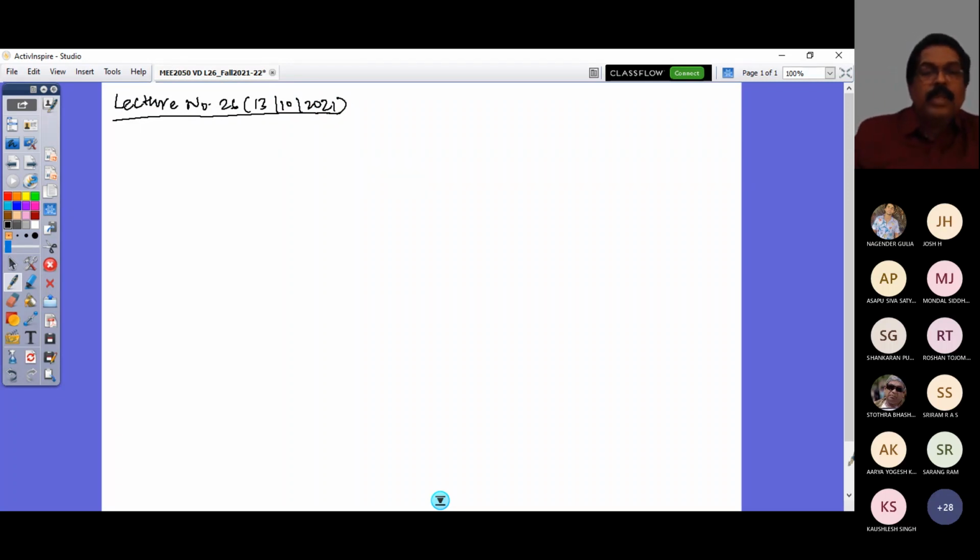What we are going to do is give you some idea about handling, as far as OEM test conducting is concerned. We have looked at three important tests in our previous lecture. What were those three important tests? Constant radius test, constant steer angle test, and constant speed test. Essentially you are trying to look at the vehicle tendencies, and when you do these tests on a real vehicle, you would be able to look at a real-time understeer gradient effect in your vehicle.